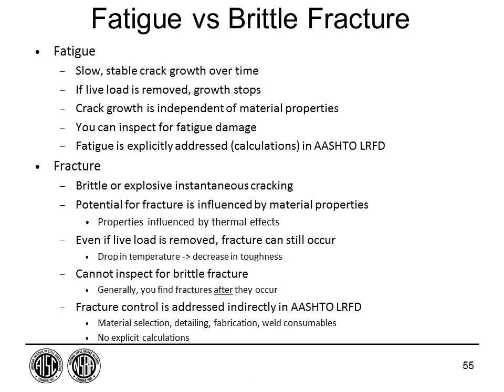So this is a good slide, slide number 55 here. It's a good summary slide of fatigue versus fracture. Like we said, we test for fatigue, millions and millions of cycles. If I stop a fatigue test, the crack never grows anymore. The crack is independent of the material. In AASHTO, we don't recognize different material strengths for the most part because of the effects of all those other things I mentioned, residual stresses and weld discontinuities and so forth. That really drives fatigue resistance. When we do inspection in the field, we're looking for fatigue cracks, and we calculate fatigue lives.